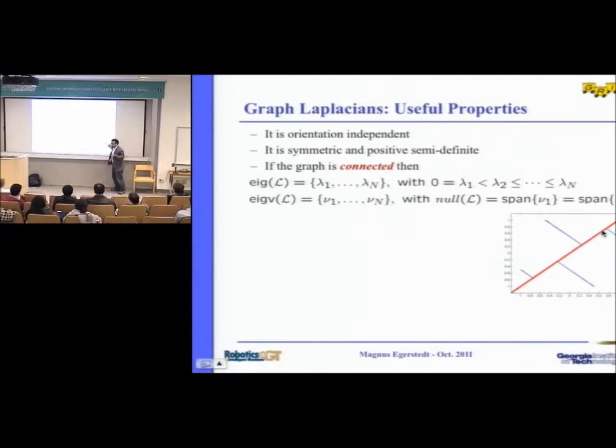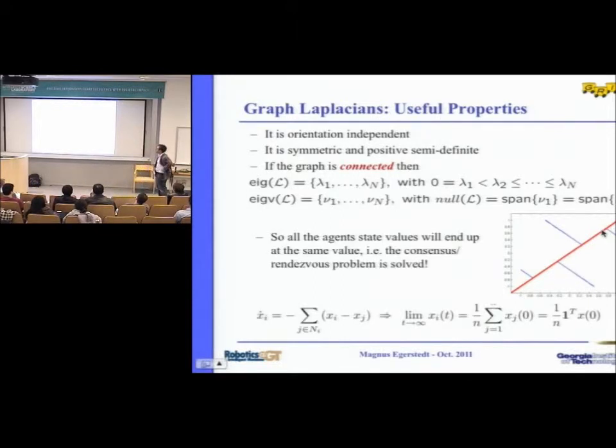When we run the consensus equation, we're all going to end up inside the null space, which is 1, 1, 1, 1, 1, 1, 1. And every component is an individual's position. So everyone is going to be at the same location. That's how you would show that this thing, in fact, solves the consensus problem. So now, by looking at the spectral properties, the eigenvalues and the eigenvectors of the Laplacian, we know when this thing works.